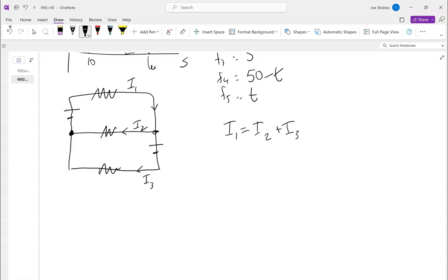Okay. All right. So when you have the big line and the small line, that's a symbol for a battery. The big line, if I remember correctly, is the positive, the small line is the negative. There's a gap in here, so you're flowing around this way. Basically, the current would go from the positive to the negative, so it would flow around that way. Honestly, as long as you are consistent with how things are going as you're reading around the diagram, you're fine. As long as you know that going this way is a voltage gain. You go from the negative to the positive across the battery. If I went backwards across it, it would end up being a negative voltage.